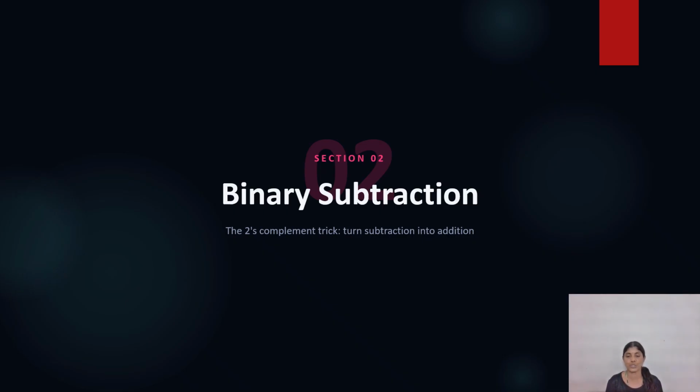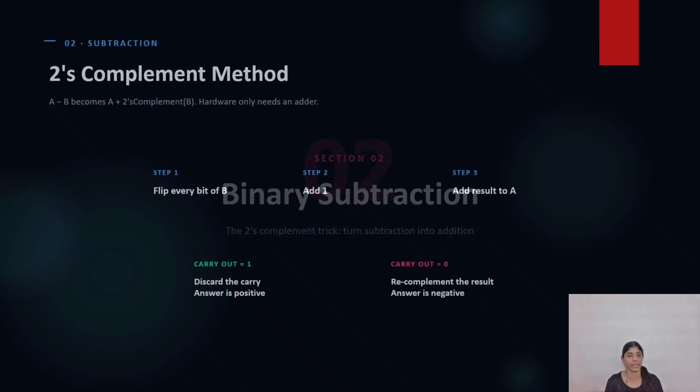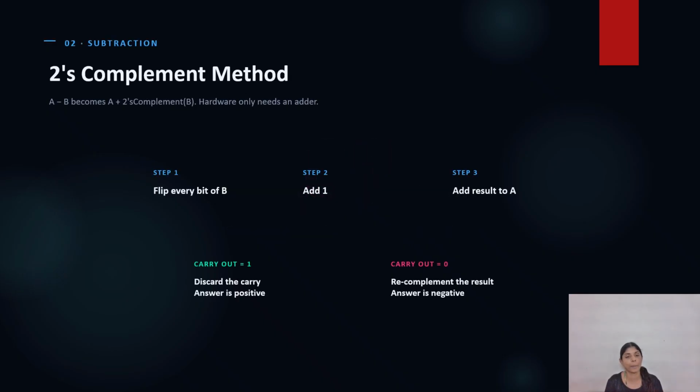The thing is, there is no direct subtraction. So instead of direct subtraction, what we are doing? 2's complement addition. Because while taking the earlier module, I told you we have used a single circuit, that is the adder circuit. That adder circuit will do both the operations, addition and subtraction. There is no separate subtraction circuit, right? So instead of doing the direct subtraction, you have to do the 2's complement addition. This is a point you have to remember here.